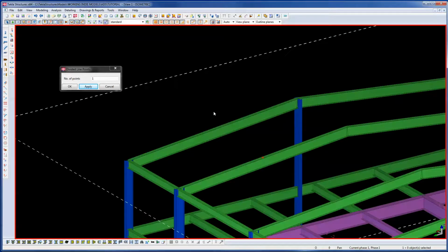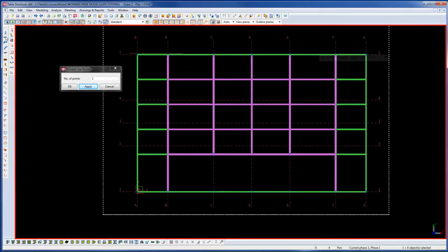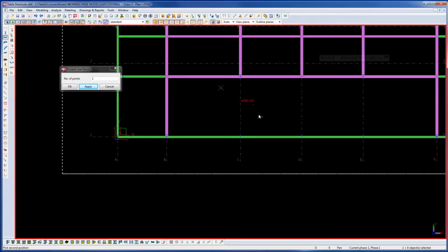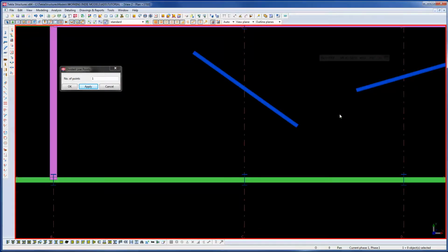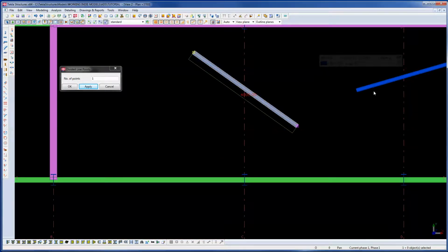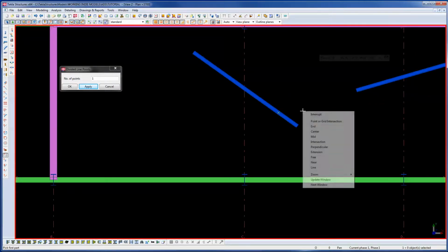While we're on the subject of points, if I'm just going to go into this view, I'm going to put in a random beam at any position. Okay, so we use this a lot for handrails. If you want the intersection point of those two. Newer versions have got a tool which will extend the beam to another beam. This is version 18, it's not available. So I use this one quite a lot. Add points to an intersection of the two-part axis. It puts that point in.